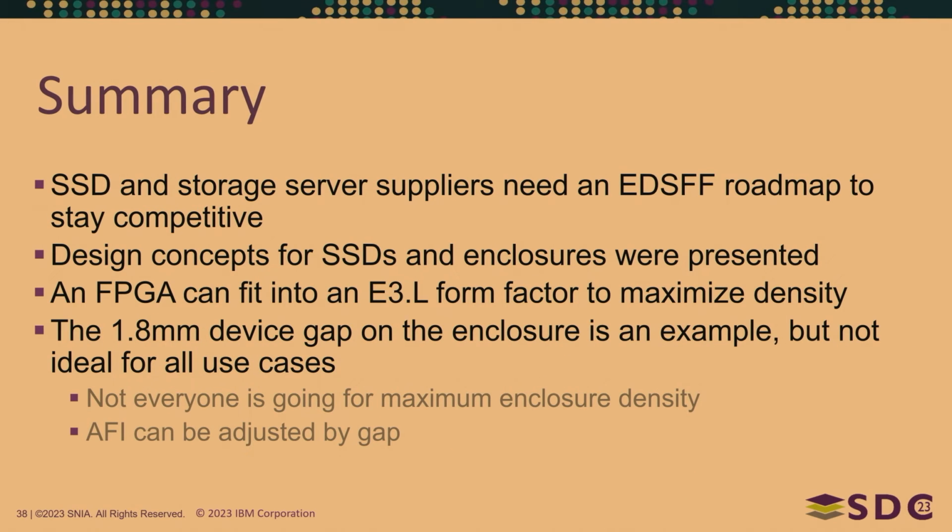So in summary, SSD and storage server suppliers really need to have an EDSFF roadmap to stay competitive. It's clear just from looking at the high-end SSD offerings that are out there that they're really going to be in the EDSFF space, and U.2 is dying out. It'll still be around, but it's not going to be there for the highest performance stuff. So I did present some design concepts for SSDs and enclosures. I think we can fit an FPGA into an E3.L form factor, despite all the challenges. That'll help us maximize density.